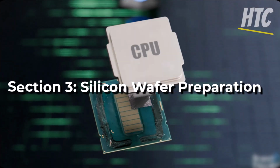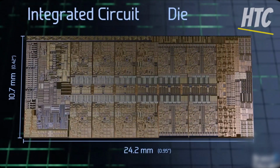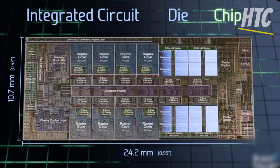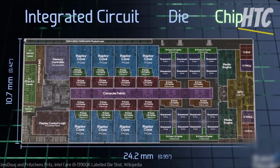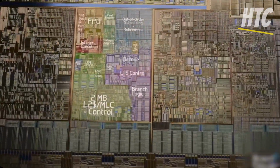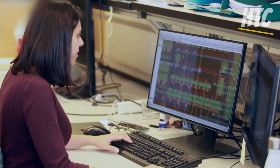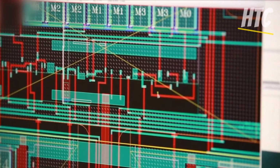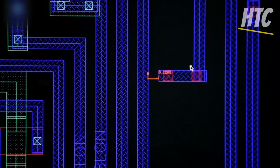Section 3. Silicon wafer preparation. At the heart of every CPU lies the silicon wafer. These wafers originate from ultra-pure silicon crystals grown using processes like the Czochralski method. The crystals are then sliced into thin, circular substrates and polished to achieve a mirror-like finish. Before any further processing, the wafer is meticulously cleaned and oxidized to remove impurities and form an ideal surface for subsequent layer depositions. This pristine preparation is essential for success in the following nanometer scale processing steps.